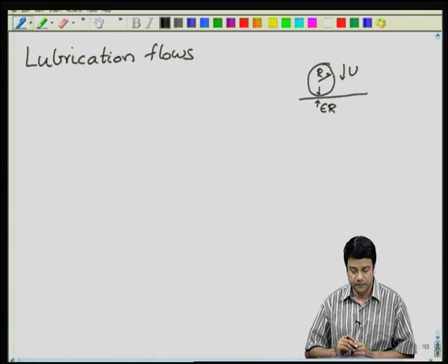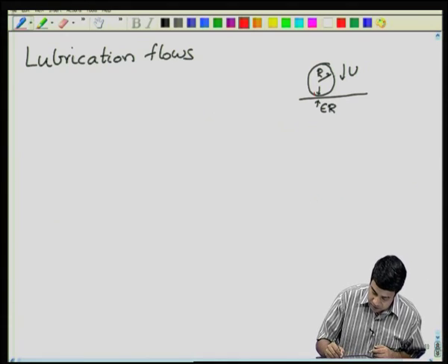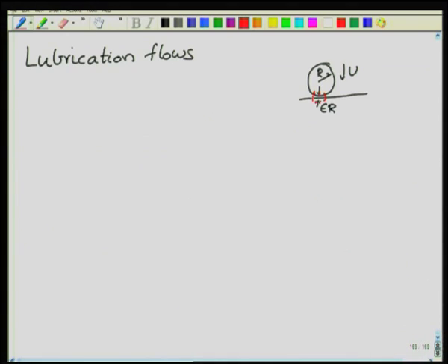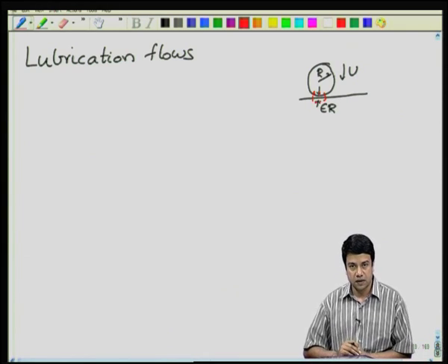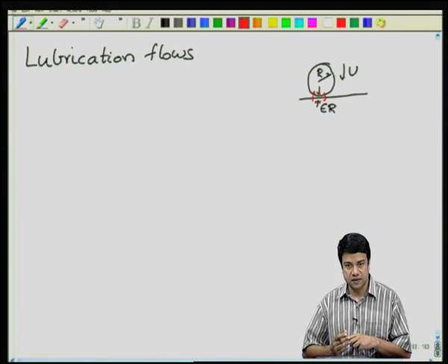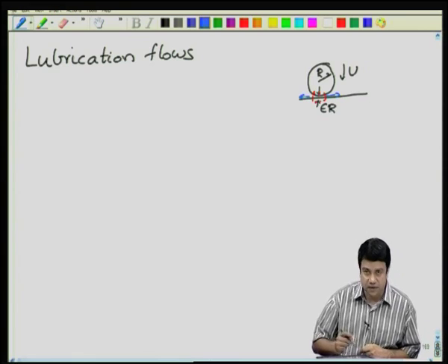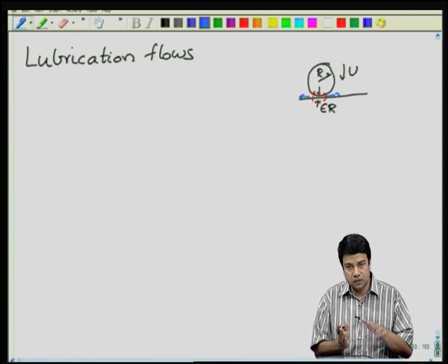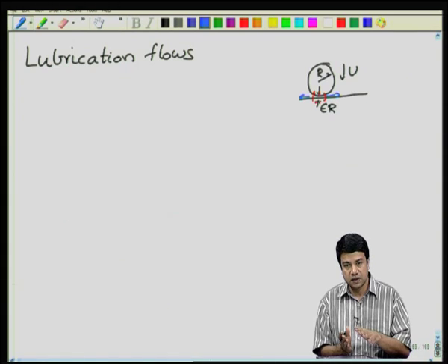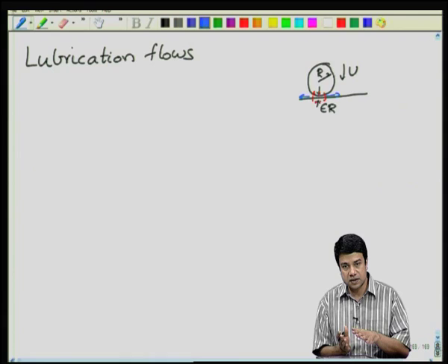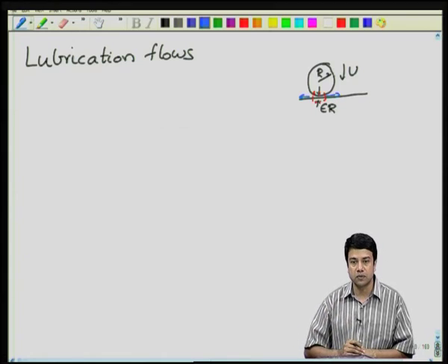How do I analyze this? Physically, I would expect that most of the force will be exerted in this little region between the particle and the surface. The reason is because as the sphere is coming towards the surface, whatever fluid is there has to be displaced out of the surface, and that fluid has to come out with rather high velocities. High velocity between two surfaces generates high shear stresses, and therefore, that force due to the shear stress in between the two surfaces exerts a force upward on the particle in order to resist the downward motion.